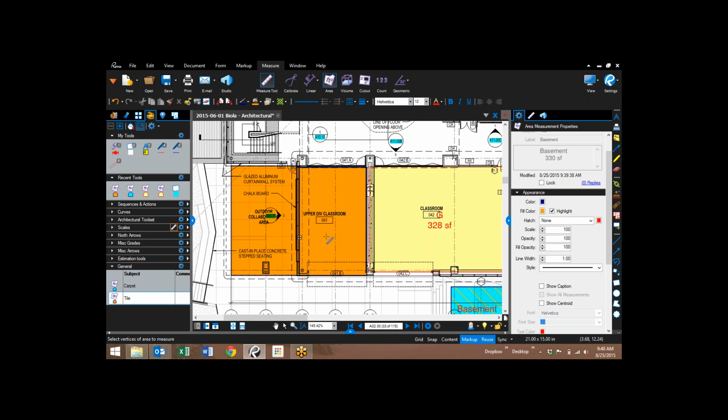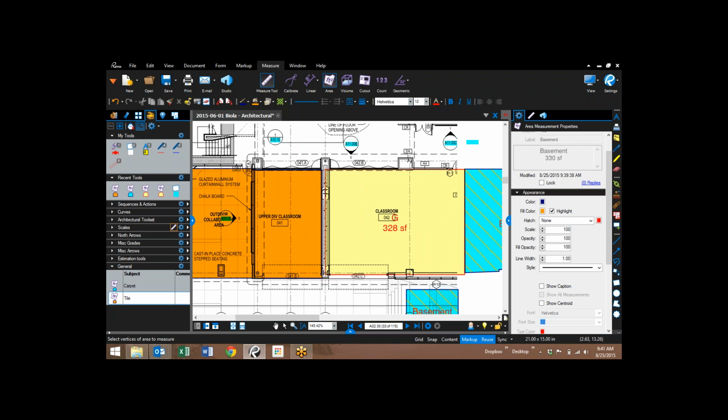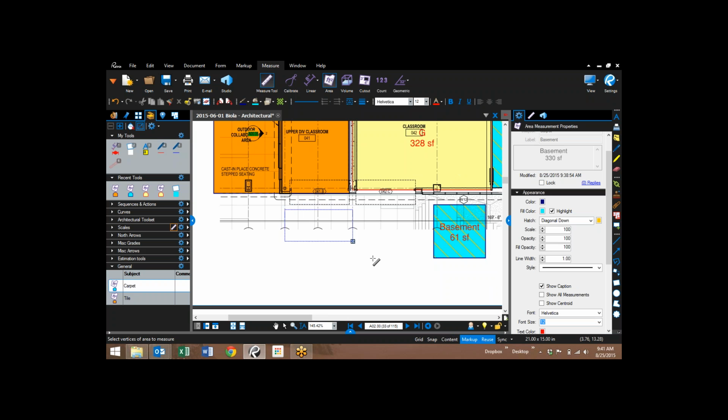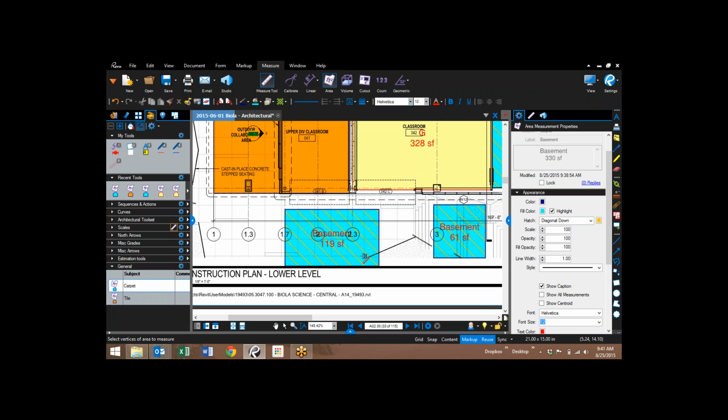So it can be quick. If you've got a lot of square rectangle takeoffs, instead of clicking around, on-screen doesn't do that. That's one thing I like about Bluebeam. So now you can see it's pointing, and I can jump to carpet now, click on carpet, and then do another takeoff with carpet. And so that's where you start getting efficient with Bluebeam.